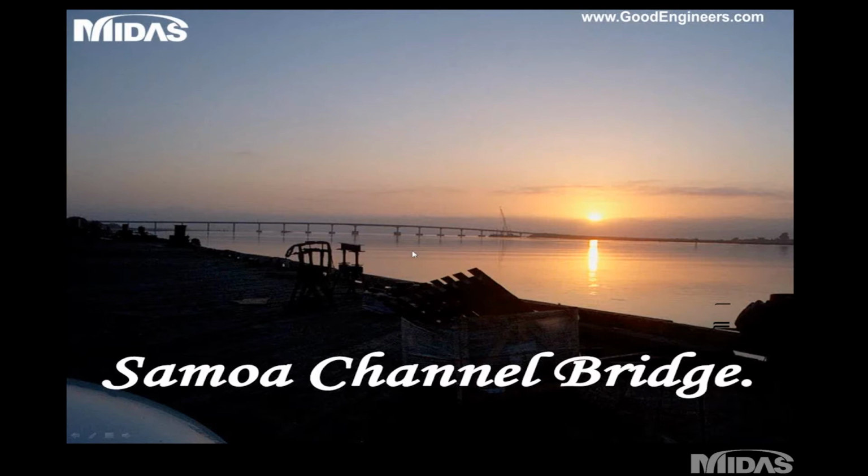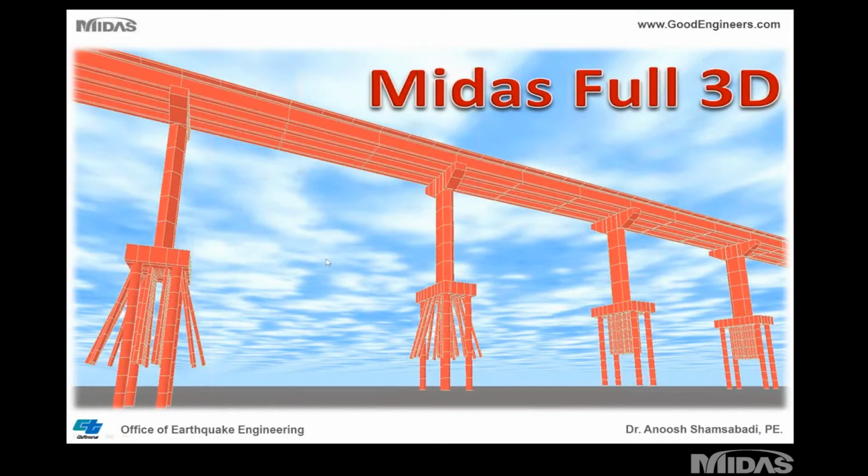So this is the schematic view of the bridge. This is a rendering that I've done with Midas, full 3D option in Midas. You can see the superstructure is composed of a composite deck, including the pre-stress post-tension beams, 4 beams, supported on hexagonal columns. Like I said, massive pile cap. This photo, which is from the rendering of the Midas, shows the pile caps, including existing piles and retrofitted piles.